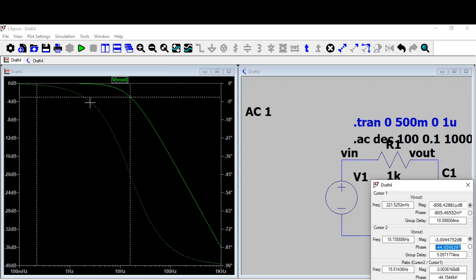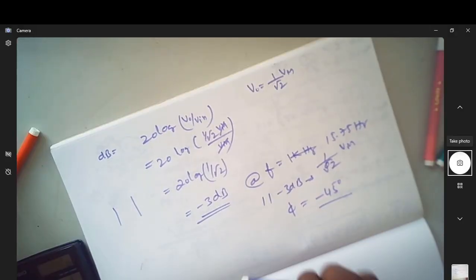See, it has got two plots. This is dotted one, which indicates the change in phase, the solid one which indicates the magnitude. So in a frequency response, in AC analysis, we will get two plots. One is called as magnitude plot, other is phase plot. In polar quantities, I think all of you know that we always have magnitude and phase.